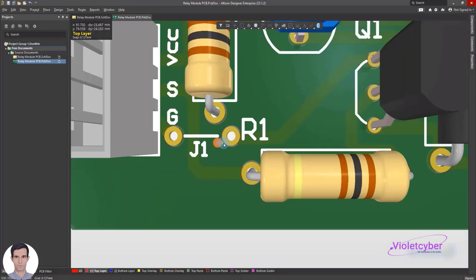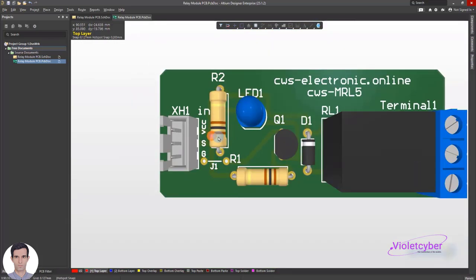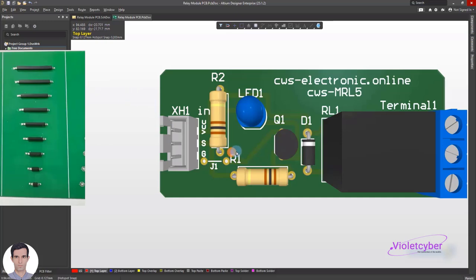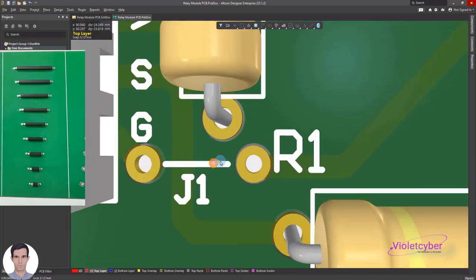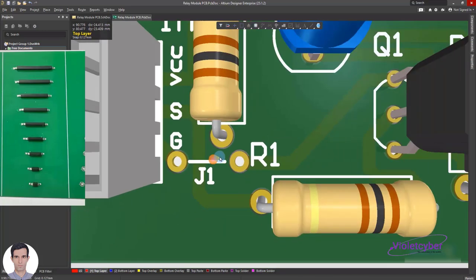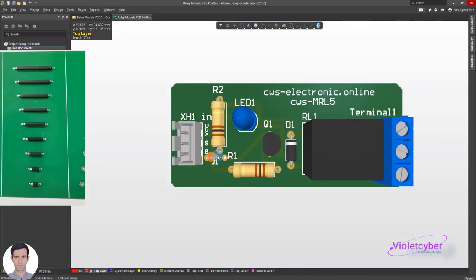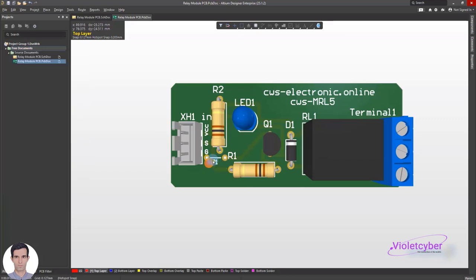What is a jumper? Now you are definitely familiar with the jumper, but again, to show you, on this side of the board I will put a board with a jumper on it, and this jumper is actually the wiring that is done neatly and cleanly on this board. As explained, it is better to use jumpers as little as possible on the board, but in this circuit we only had one jumper. First, with the design details, this jumper could not have been needed. Second, since there was only one, there is no problem in putting a jumper, especially since this jumper is on the negative side and is only going to connect the power supply.